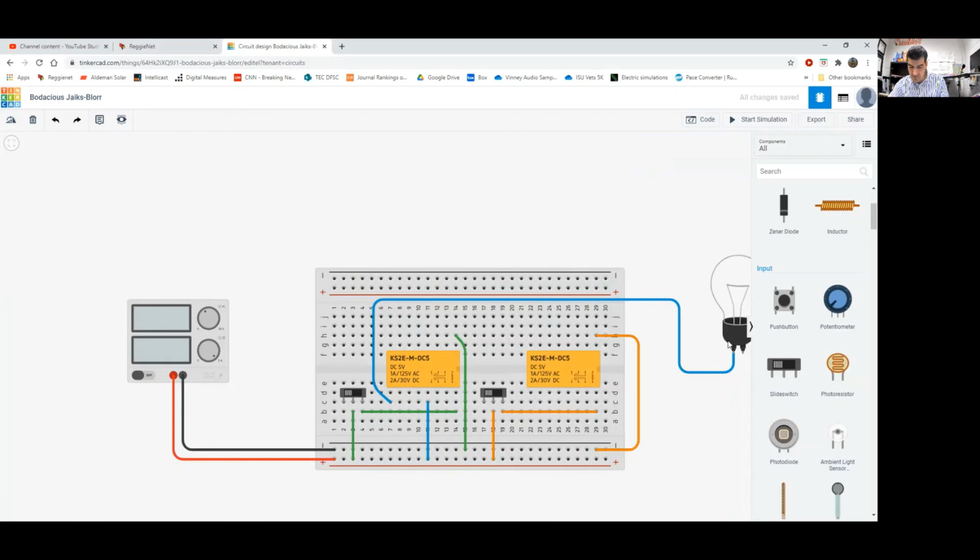And then the same thing over there for relay number 2. I've got to go from the power supply to the common of the contact, and that needs to be blue because it's in the third rung. And then I need to go from the normally open contact associated with that common, so that's over here on terminal 9. And I need to go from there also to the input of the light bulb. These are in parallel. So once again, I'll make it look better in a second, but it's going to come over here.